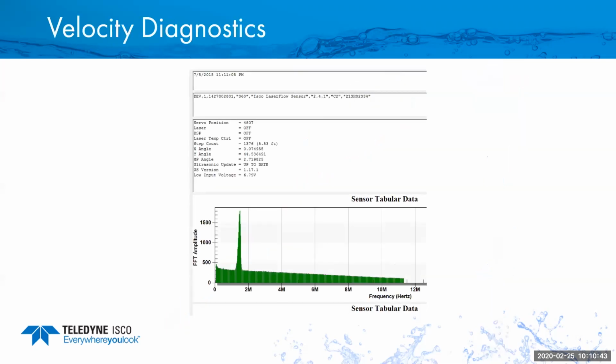Okay, the key thing with the laser, and one thing I like, is when I get a reading, I want to know that that reading is correct. We are one of the few companies that probably push a lot of the diagnostic capability of what the laser is doing, or all of our meters are doing. And if you look at this, what you'll see is we have a return frequency spectrum. The bottom frequency is the speed of the water. The faster, it's more to the right, and then the slower the velocity, more to the left. We take that velocity reading, we scan it 10,000 or 5,000 times. The more that agree on the return, the better that Doppler shift looks, or that spectrum looks. When we look at this diagnostic, I can tell remotely, I can tell after the fact, or even when you download data, if that laser was working right. So now I have confidence in the velocity reading that I'm getting.